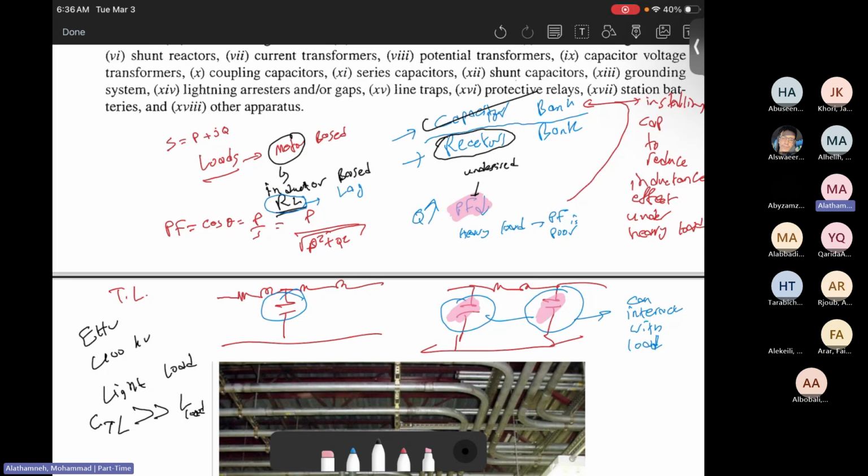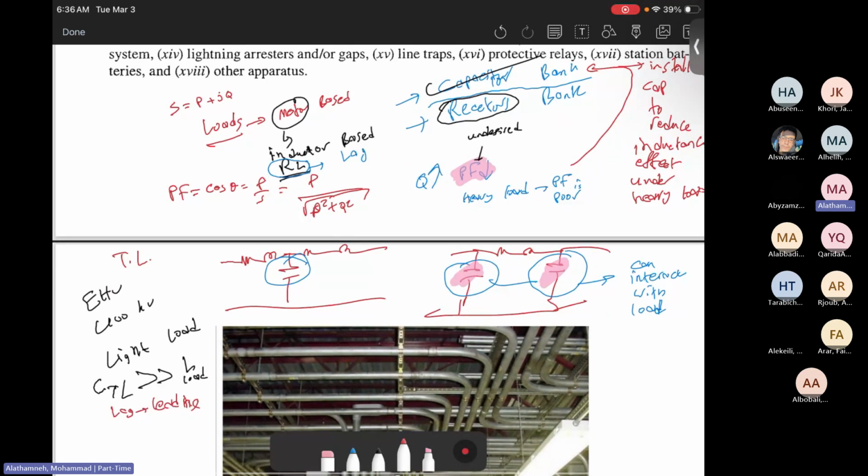So as a result, the inductance of the load will not be sufficient, it's too small. Therefore, the capacitance is higher. As a result, this will make the power factor move from lagging to leading, or we have extra reactive power that we need to remove. That's something undesired. We need to remove it. So how can we solve this situation?